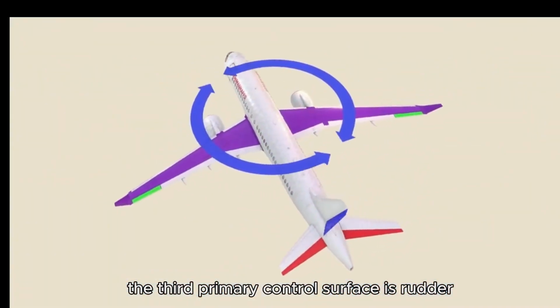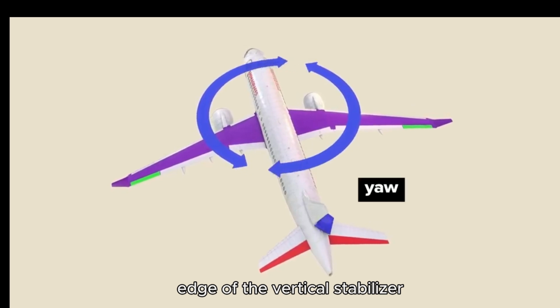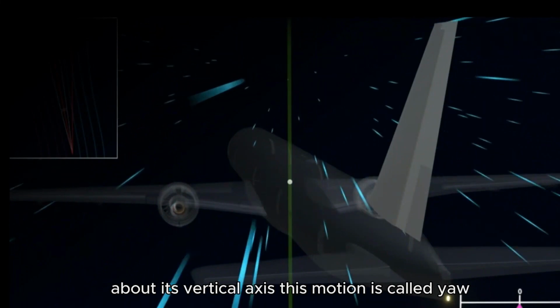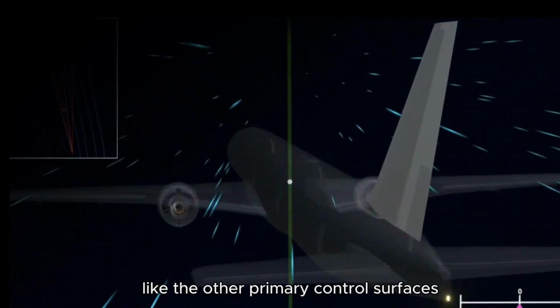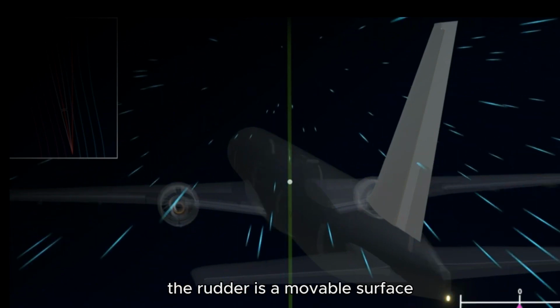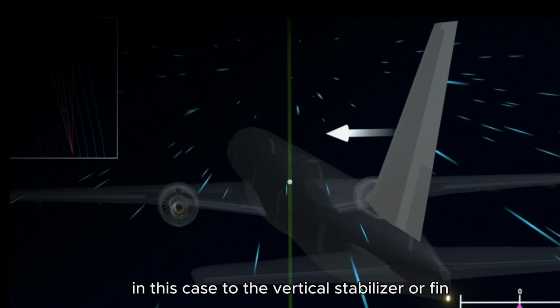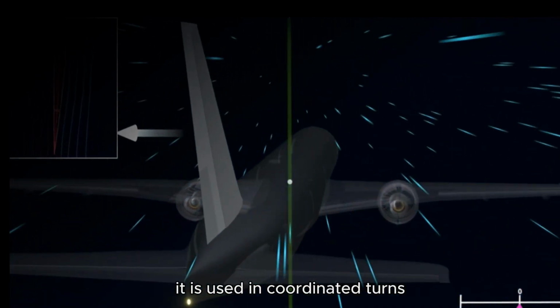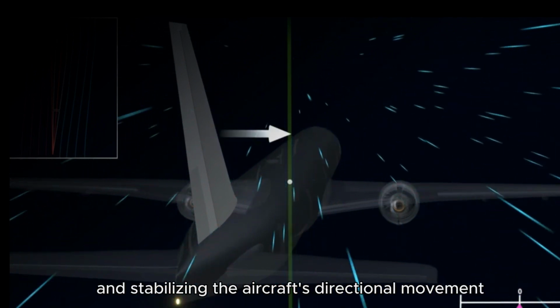The third primary control surface is the rudder. The rudder is located on the trailing edge of the vertical stabilizer at the tail. The rudder controls movement of the aircraft about its vertical axis. This motion is called yaw. Like the other primary control surfaces, the rudder is a movable surface hinged to a fixed surface, in this case, to the vertical stabilizer or fin. It is used in coordinated turns, managing crosswind landings, and stabilizing the aircraft's directional movement.